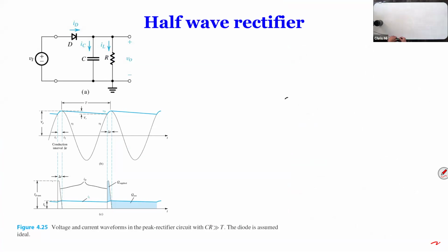Okay, guys, good morning. So last week, we stopped at our last lecture. We stopped here at the rectifier, and then we talked about how this gives you half of the wave if you don't have a capacitor. If you have a capacitor, you can see that the voltage actually charges to this peak if you don't have a resistive load connected. But if you do have a resistive load connected, the voltage is going to drop a little bit because energy comes out from the capacitor to supply power to the resistor.